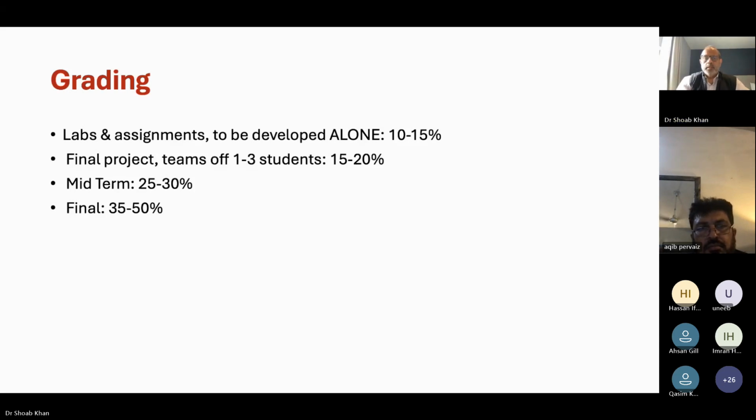Sir, I have a question. Do we have to translate the ML part or do we have to design hardware? Yeah, you need to take the ML part and design the hardware to execute that ML part, the machine learning part. Sir, okay, like the sorting algorithm I did: you have the sorting and you place multiple comparators so that they do all the comparisons in parallel, not sequentially as is done in software.